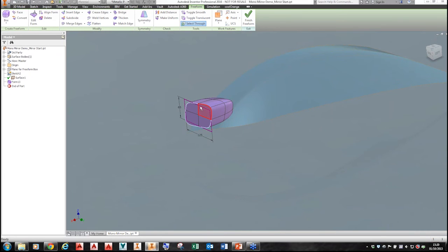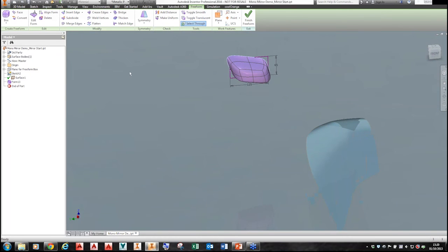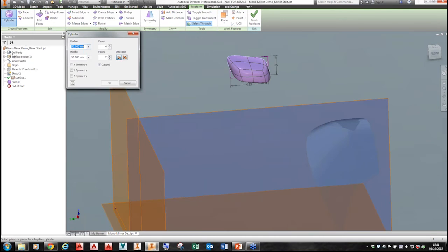So what I'm going to do is create the connecting arm which goes back down to the wing to start then blending the full component for the plastic housing. To do this, we're going to generate a new freeform. I can still do it within the freeform environment. So over to this side over here, I've got create freeform. From the drop down I'm going to choose cylinder. And again, I need to position initially where I want to create the cylinder. So I'm going to choose a radius first.